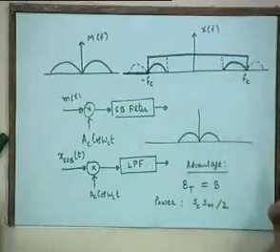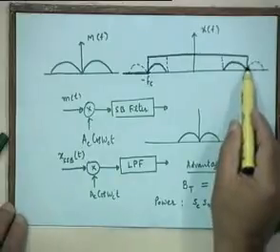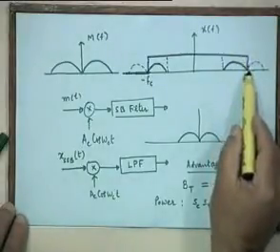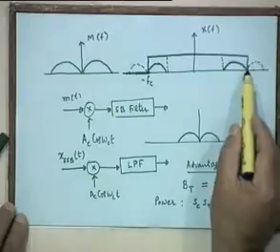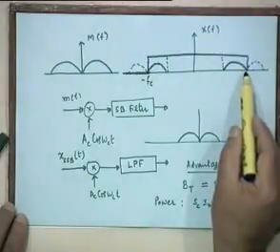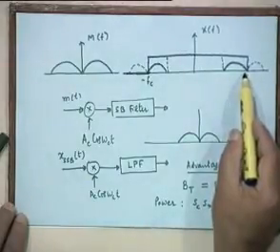For an ideal tuned filter, the Q is infinity, but as Q becomes finite, as it becomes smaller and smaller, the bandwidth increases, right? So you require a Q of a suitable value, and typically because you require very sharp cutoff, you require fairly high Q filters, very high Q filters.